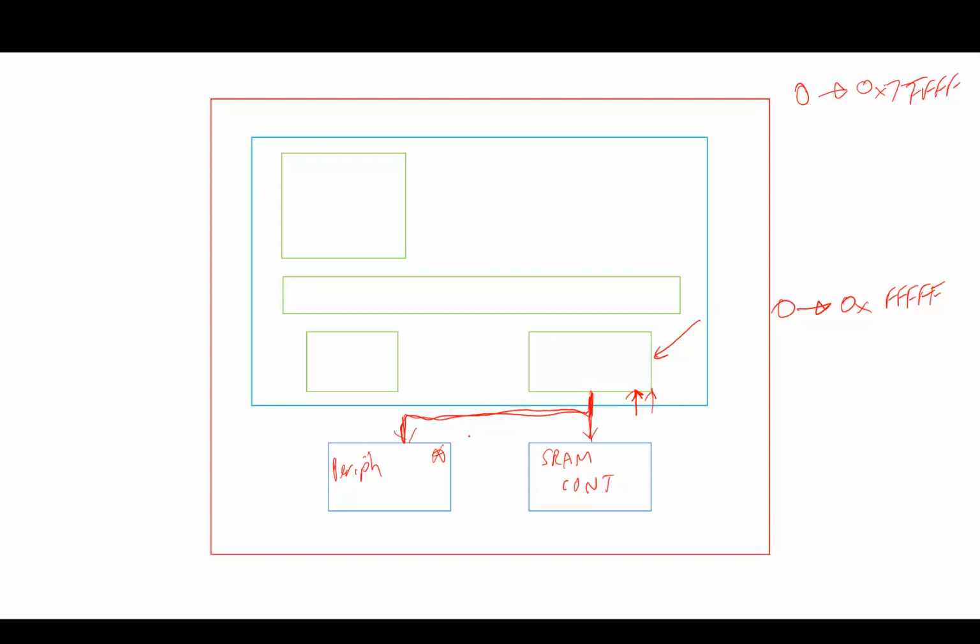So you need to write some logic that decides when to take this acknowledge, or when to take this acknowledge. There should be some kind of switch that goes between those two. And the same for the read data. There should be a switch between choosing the read data coming out of the SRAM controller or the read data coming out of the peripheral module.